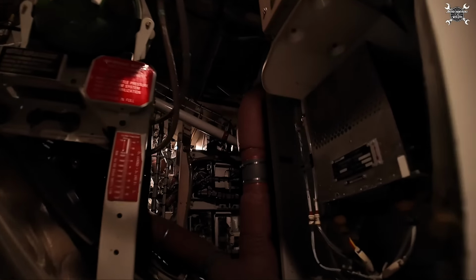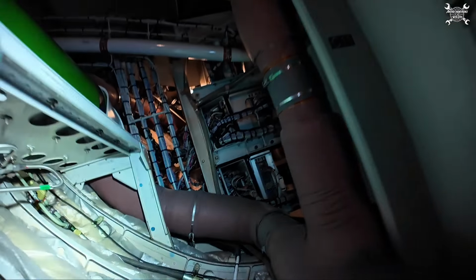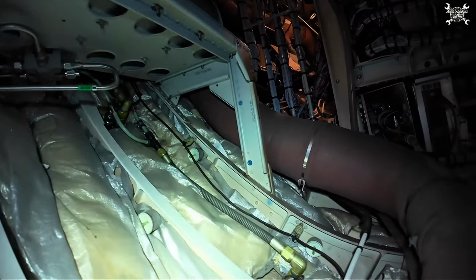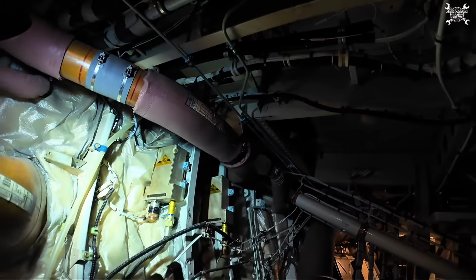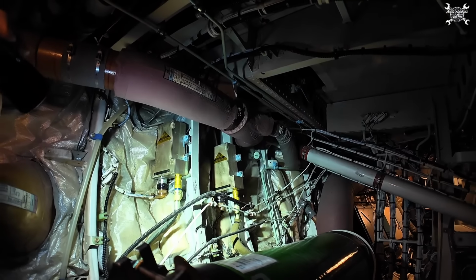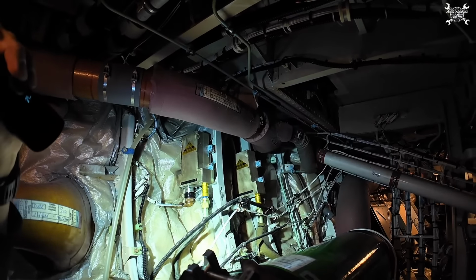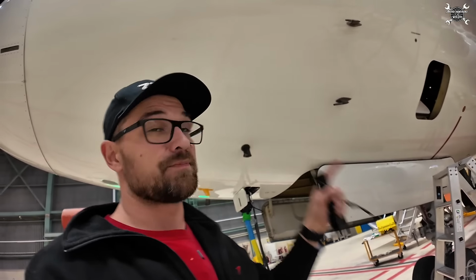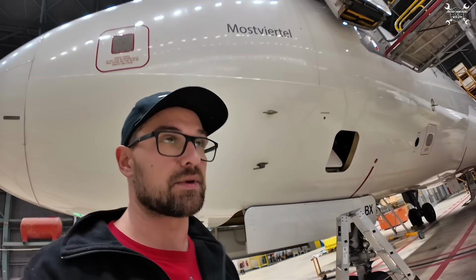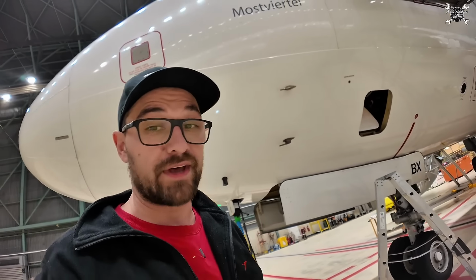And here you can see the probes, or the connection to the probes, and air data modules are up here. So those 2 modules transfer again information to ADIRS. And by the way, each of these probes is equipped with a heating system, and this way will avoid buildup of ice. And today we're gonna talk about pitot probes and static ports for system 1 and 2, which is for first officer and captain.